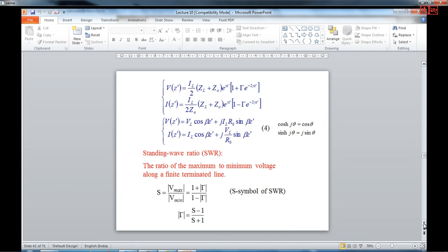If the load impedance value is different from characteristic impedance of the line used, then you are going to have a reflected voltage wave traveling from load to the source and giving rise to both the waves, but they are mixed up. The reflected and the incident waves together only will be what you can observe on a transmission line, which is known as a standing wave.